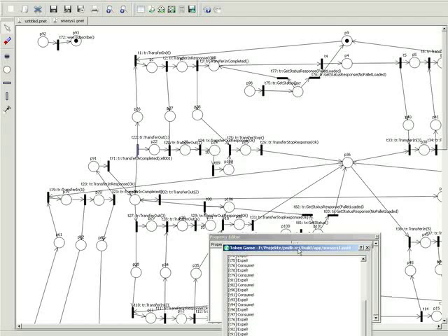The production logic is designed with high-level PetriNet models which follow the status of the production cell. When there is a change of state in the production line, the model is updated with this new information and can react, issuing control calls as required to the participating devices. The advantage of using PetriNets for designing the control logic is that these can be mathematically analyzed and validated, and also provide flexibility for decisions.